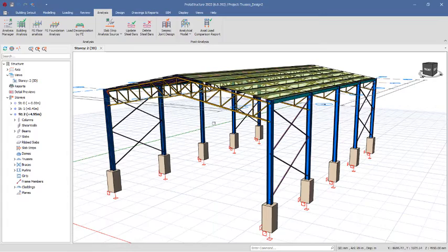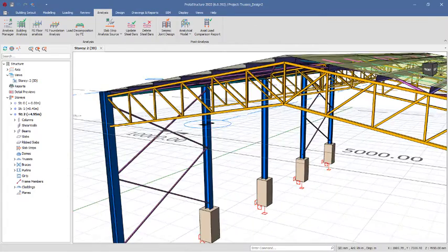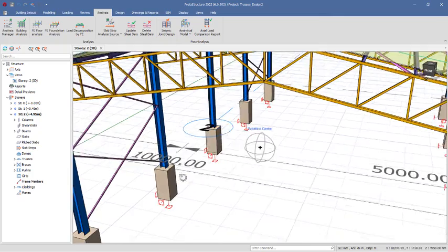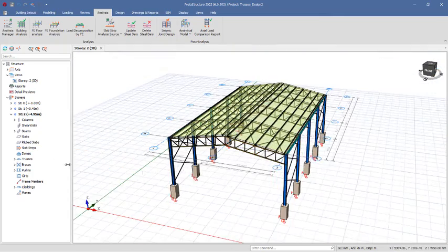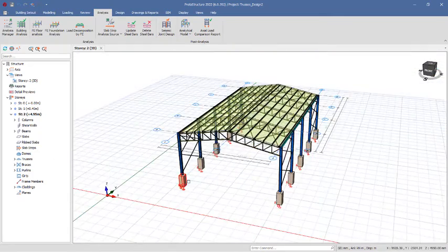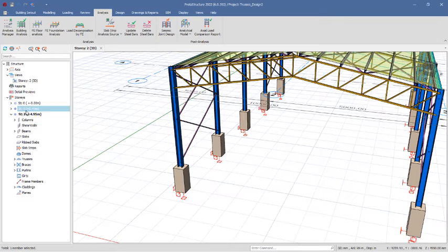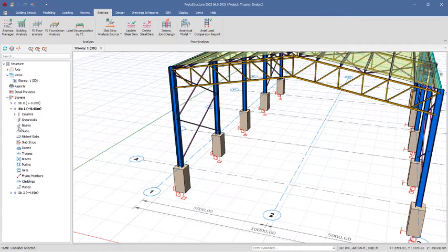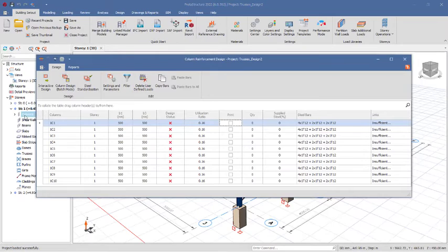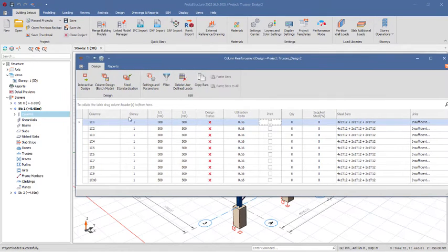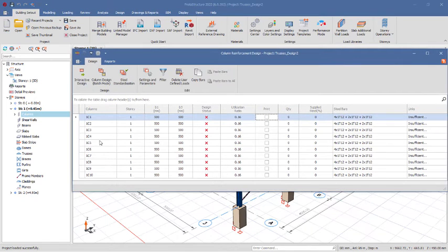So at this time, we are going to be checking the structural elements to see if they have actually passed the design successfully. At first, we'll check the reinforced concrete member, which is the column right there. You navigate to story one, because that is the story where we have the columns, and then select it, right click. So we will be considering the columns. When you select the active story of the columns, you have this. These are the RC column sections. You see it is not designed.